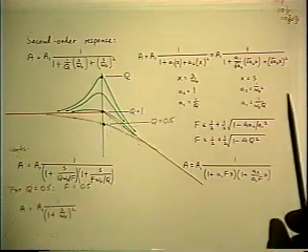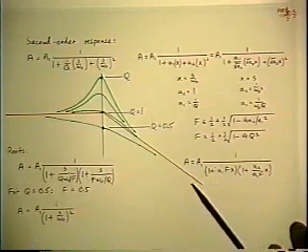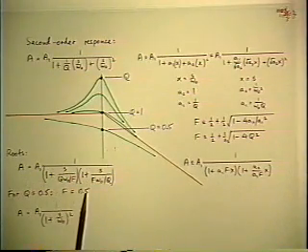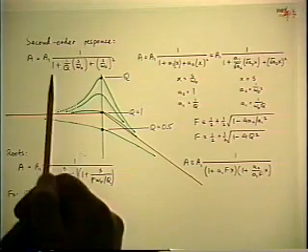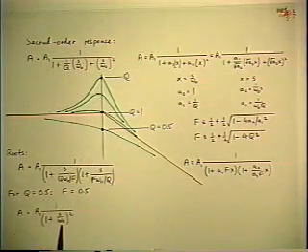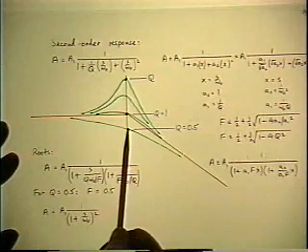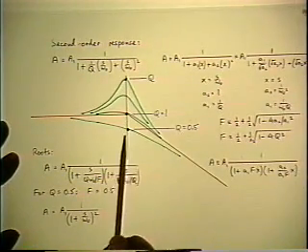The special case of Q of 0.5 means you have two equal real roots, which is the boundary with the complex root case. And we know that F is equal to 0.5 if Q is 0.5. This allows you to factor the quadratic into two equal real roots, which means that you would be 6 dB down at the corner frequency, consistent with the fact that that's also the value of Q.